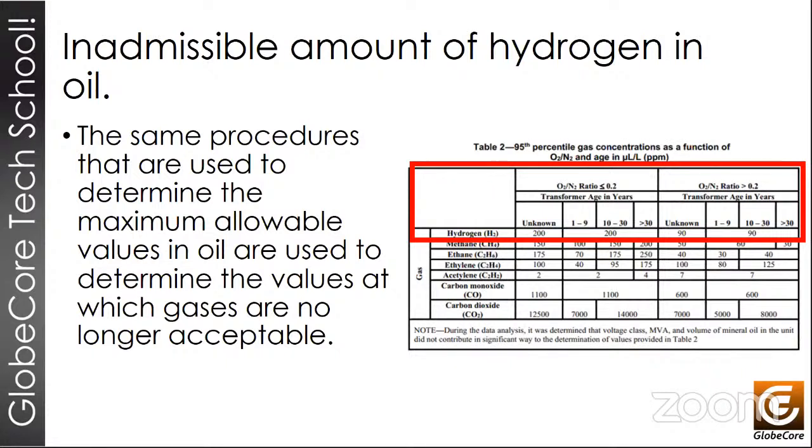Now, if we think back and recall the previous table, we'll see that there is a range of values that are considered to be warning ranges, because if the hydrogen value exceeds the values from the previous table but does not exceed the values in this table, we can determine that the transformer is in a problematic, questionable state, and it's necessary to conduct a deeper investigation of the characteristics of the possible fault problem, where we'll also take into account any values from other tests that we can perform, which is of great value for determining the exact possible fault and identifying the subsequent repair process.